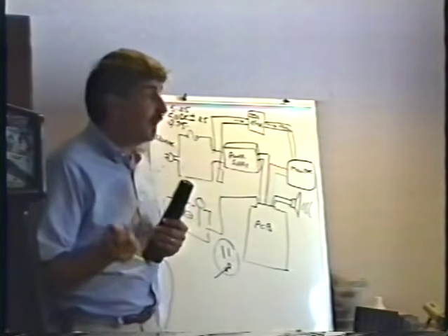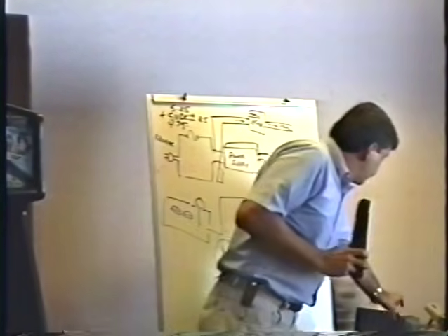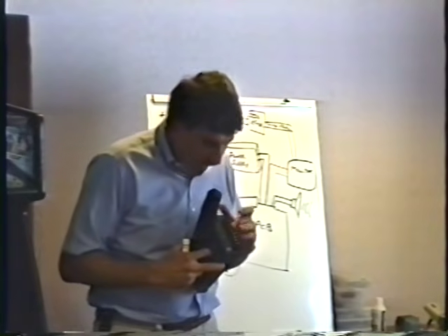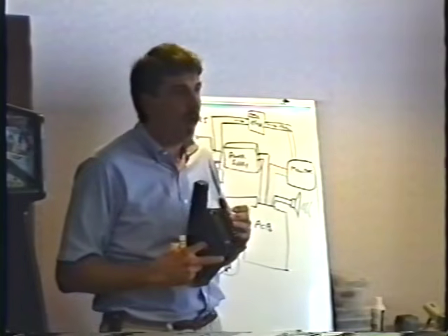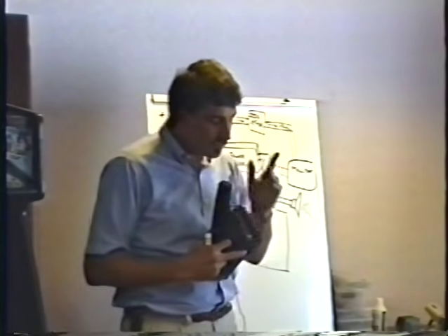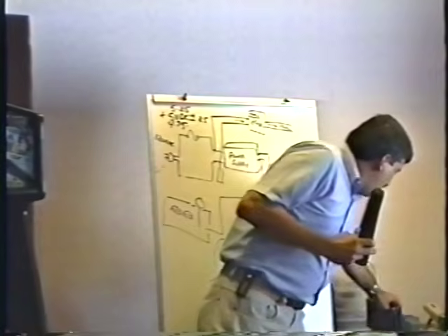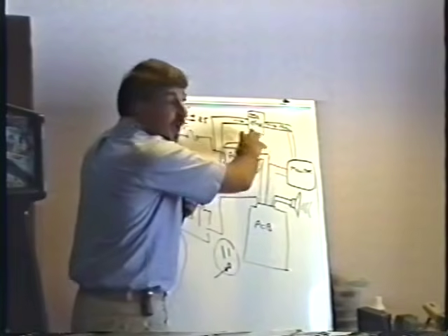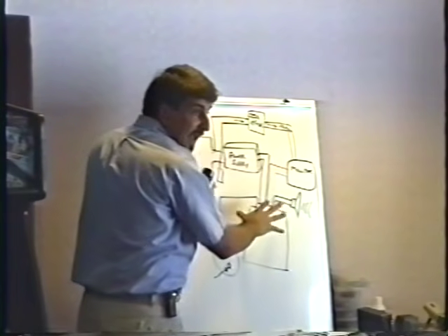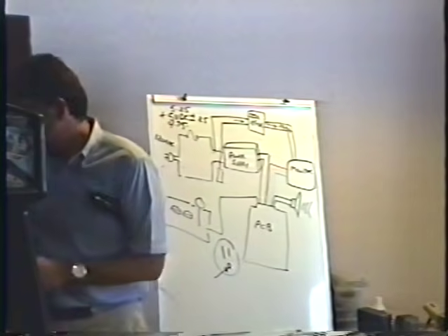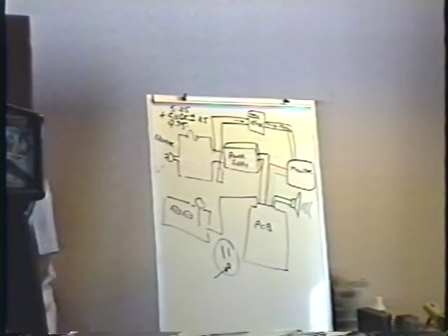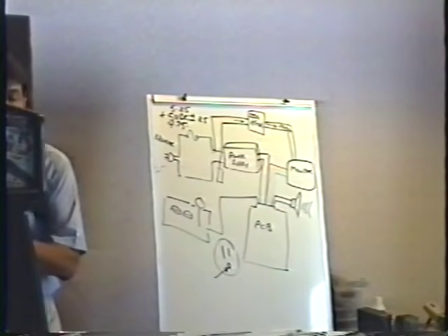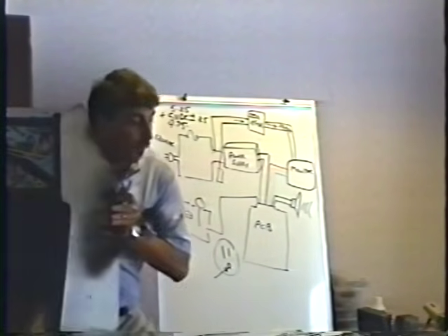But where the heck are you going to check the voltage? Well, the logical place is the same place you checked it before. You go, well, I'll just put one meter lead here on ground and the other on plus 5 and adjust it to 5.1. Not even. Not even. And the reason why not is that by the time the power gets out of the power supply, by the time the current gets out of the power supply, through the wiring harness, through the connector, it's real easy to lose a few tenths of a volt. And since the voltage is so critical, it's very important that it's 5.1 volts on the logic board.